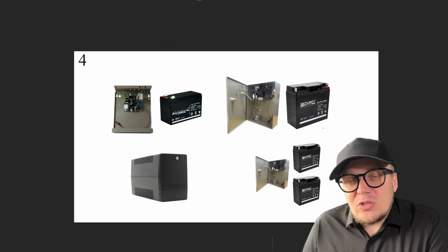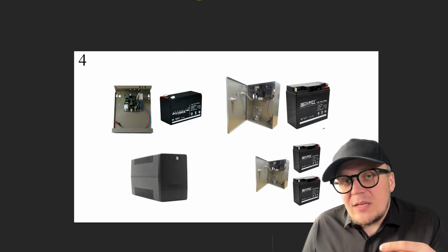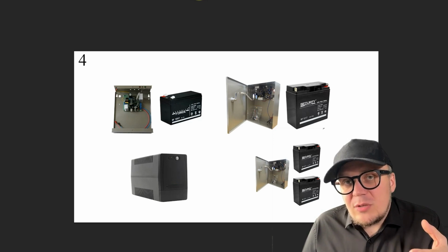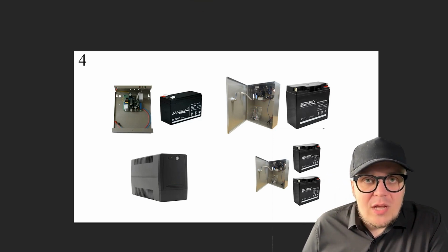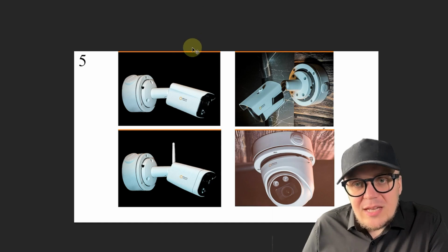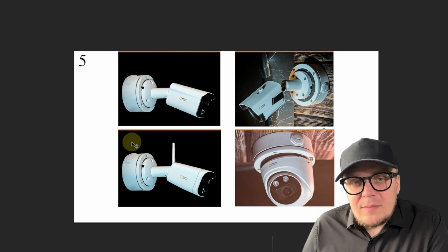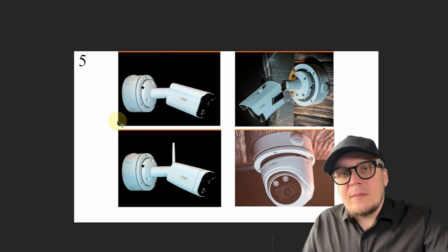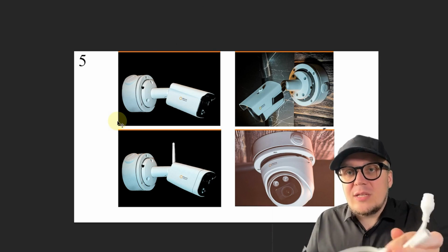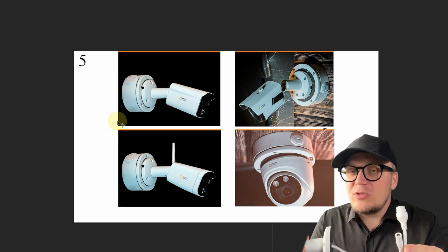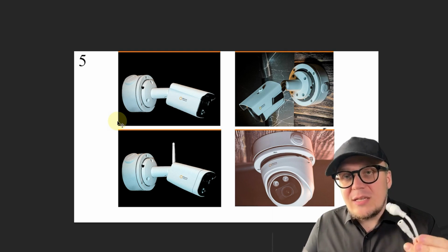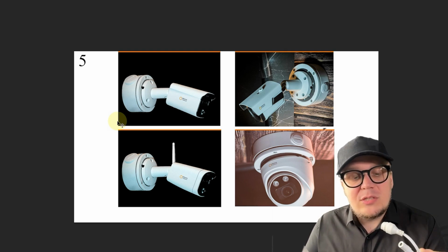A typical situation with voltage fluctuations is not only thunderstorms, it is also when someone on the street turns on a welding machine, and it is when, in general, you have some kind of old, worn-out wiring outside. The next typical problem is when you haven't sealed the connector. All surveillance cameras have a cable right here. This is an outdoor surveillance camera. It is dust and moisture resistant, operates down to -60, but this connector needs to be properly sealed.